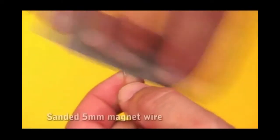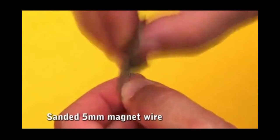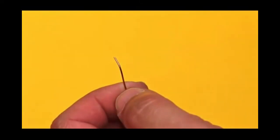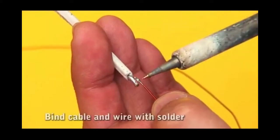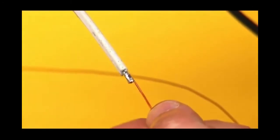It is necessary to sand a few millimeters from the tip of the wire to remove the varnish layer, the electric insulation from electricity and moisture. Pre-tin the copper wire tip. We connected the wire and cable, melting the solder with the soldering iron.